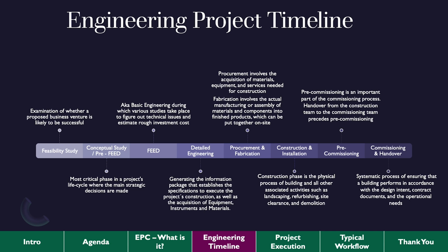And that's the whole point of having a data sheet. Most importantly, it's very clear what you need. Because whenever you are filling in these pressures, temperatures, fluid, and how much, for example, partial pressure of hydrogen, it becomes very clear to the vendor how he is going to spec that given compressor, for example.